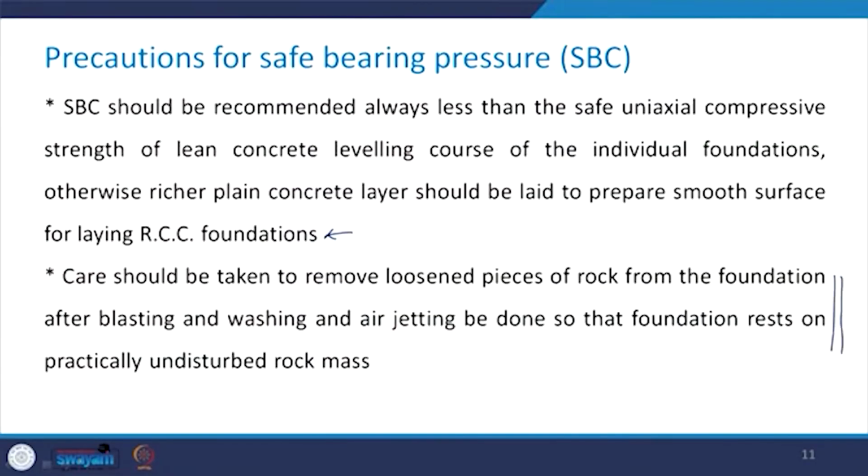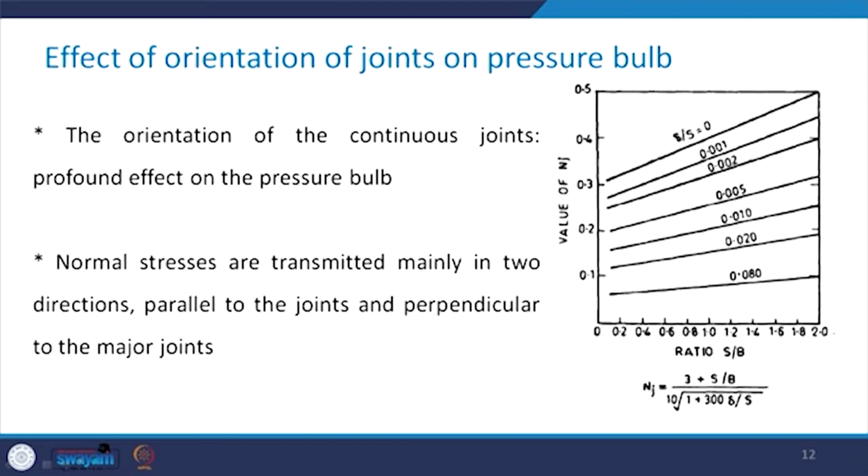If this is not done, then whatever bearing capacity the foundation would have had on the undisturbed rock mass will not be achieved if you are not carrying out this particular step, that is washing and air jetting. So, one needs to be extremely careful.